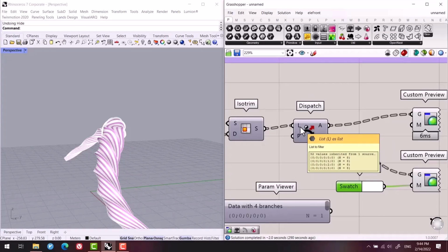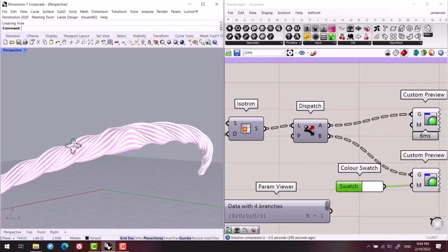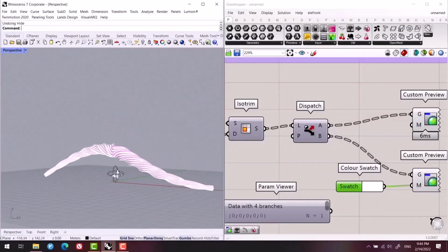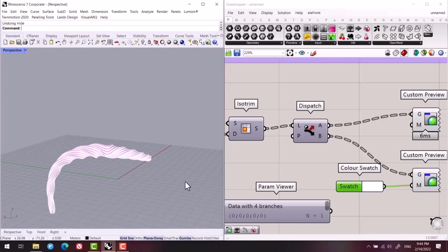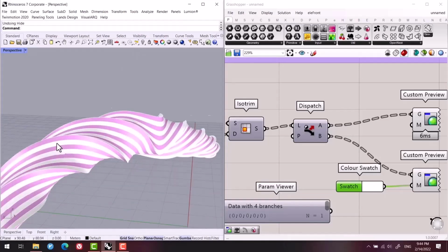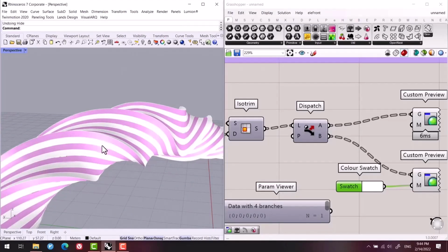or even creating some new panels. So what should we do if we want to have the panels? Here we can start by minimizing the divisions. Right now we have divided each of the faces into 8 ribbons, since I specified 8 in Divide Domain 2.